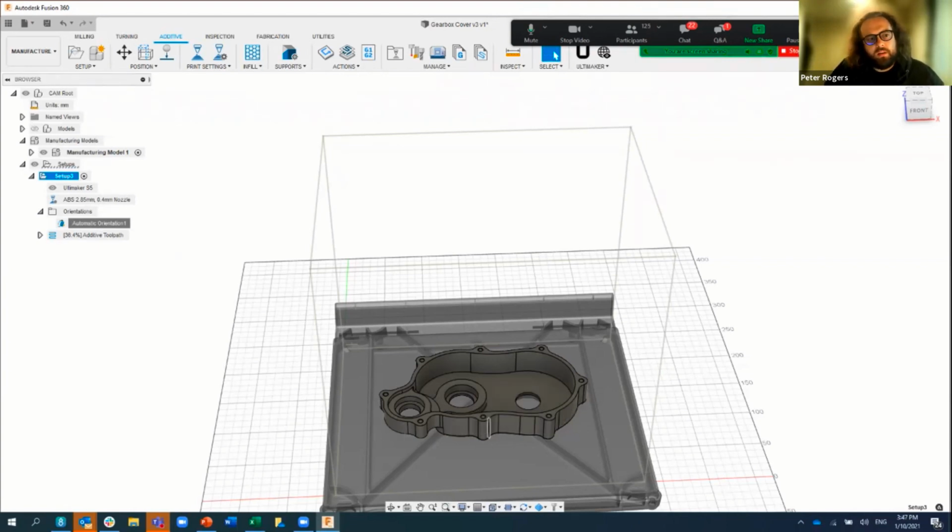If you're familiar with latticing and these sorts of things, like what we're looking at with the shoes, it's going to be taking the design and creating an infill style geometry within the geometry. The difference with these is that the infill is created on the slice level, so it doesn't actually live within the geometry. But when you look at the way that the toolpath is generated, the G code will have created that nice infill to help us reduce the material. It also helps us to reduce the build time, and it just helps to keep the overall costs down.